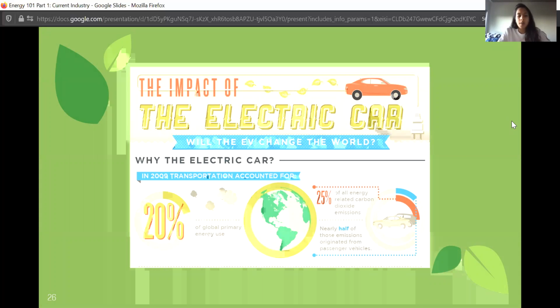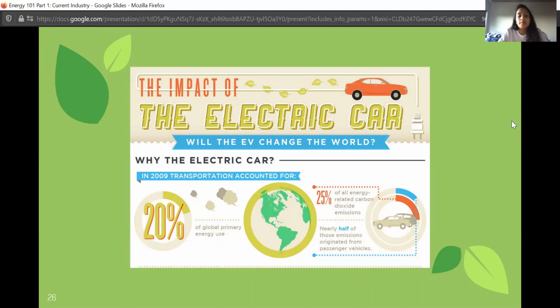There are huge steps forward being made by manufacturers in terms of battery power and system efficiency, both of which contribute significantly to the usability of EVs in particular. Battery aging, which is the gradual breakdown of a battery using successive charges, is a real issue, and many manufacturers are working on alternatives to wet type batteries, but EVs will remain sold in smaller numbers until this issue is resolved at least. The purchase price is also a significant issue, and governments must put pressure on manufacturers to reduce price, which makes these vehicles appeal to a greater market.